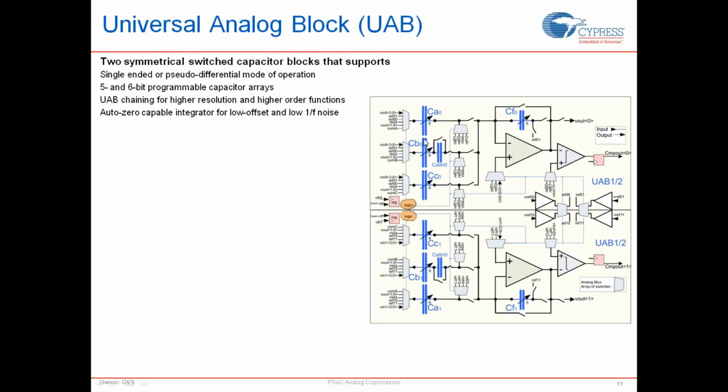You could also have your input capacitor being sampled in one phase, and switch phases based on another signal. That is also a possibility, which is called a modulation signal. So now what you've achieved is you're having a positive gain in one phase, and then the modulation signal switches, and you have a negative gain for the circuit. That is equivalent to making a mixer.